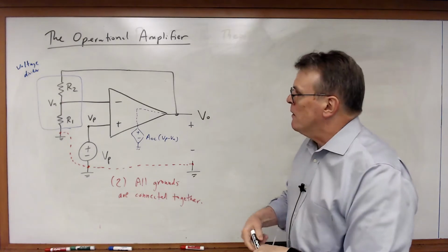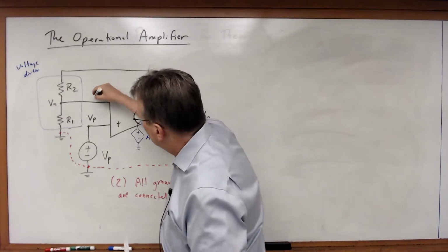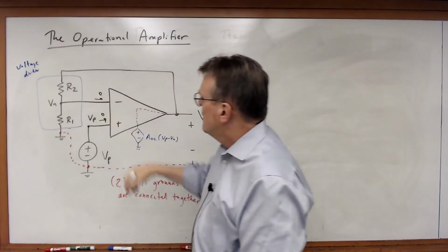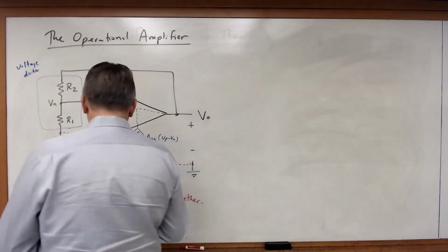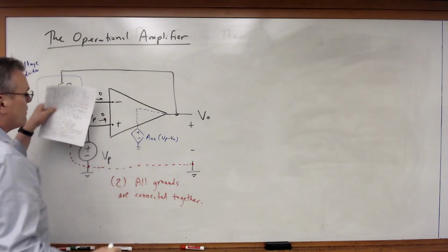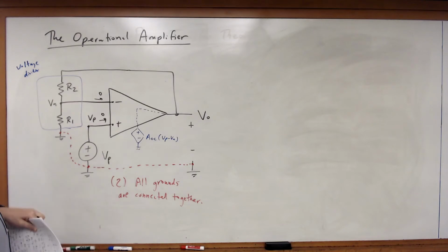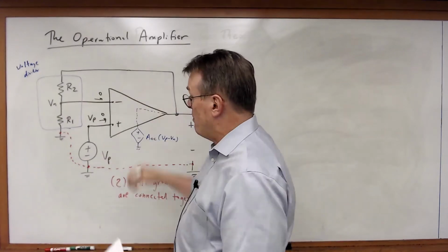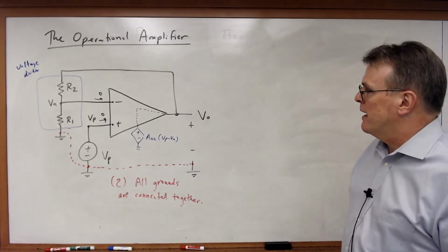Okay, now first of all, given this idealized source, we know that the input currents to the op-amp must be equal to 0, because remember, with that simplified circuit, we just assumed we had just wires on the inside so that the dependent voltage source could reference those voltages. So the current must be equal to 0. They're just open, it's open circuit, just the ends of wires inside the op-amp.